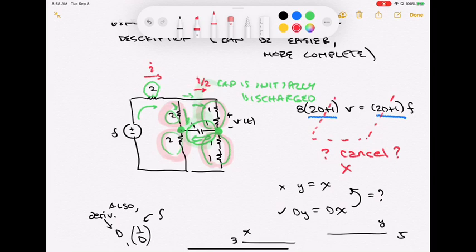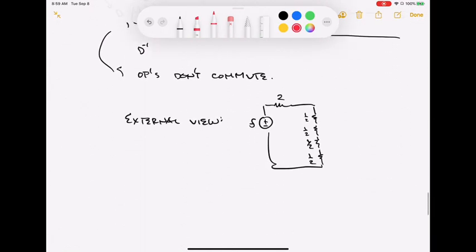That I by 2 is going to go through a 1 ohm, a 1 ohm, a 1 ohm, and a 1 ohm, something along those lines. So each one of those is going to get an equal drop across each one of those 1 ohm resistors by the half of the current. So if you were just looking at it from the output variable V standpoint, they look more like a 1/2 ohm type of resistor that you would see in there. So our plus minus V would be acting on something like that.